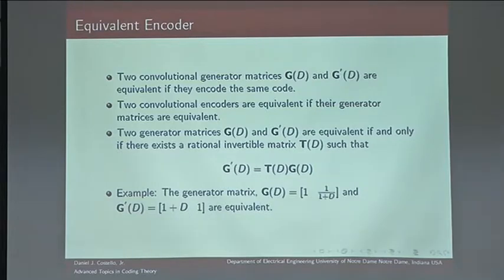Well, it is important in a turbo coding application, because in turbo codes they use two encoders, and the first encoding is done with a particular input sequence, and then the input sequence is reordered, interleaved, and permuted, and it goes into the second encoder.